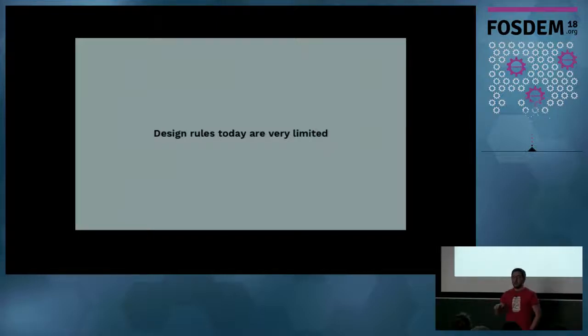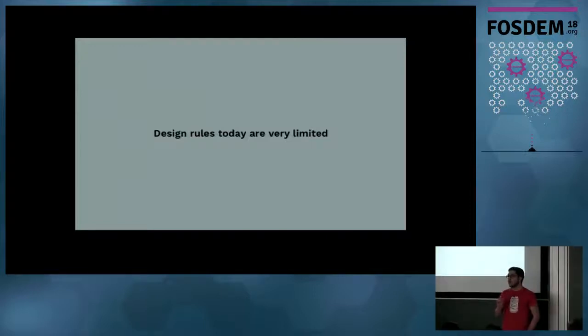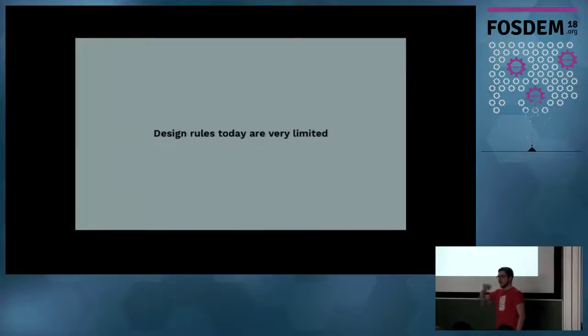Please don't go below. But if you are able to maybe draw the tracks a little bit wider, why don't you do that? And the reason is not because I told you, but there should be some kind of a window. Something like, don't go below this limit, but if possible, please stay above. Because it's not just about finding a way on how to manufacture a board, it's about finding a way that every PCB will be correctly manufactured.